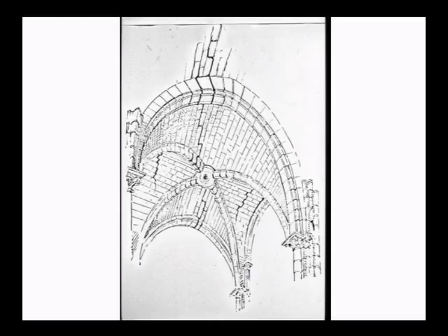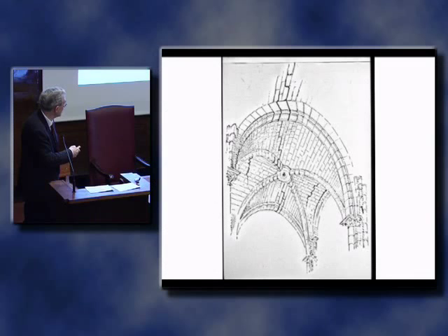If one looks at a practical quadripartite vault, one sees cracks of various sorts. There is this crack somewhere near the center. There's a crack a meter or two in from the end, and another crack at the end of the vault. And these occur very regularly in almost all vaults, and they are due to movements, again, not to stresses.